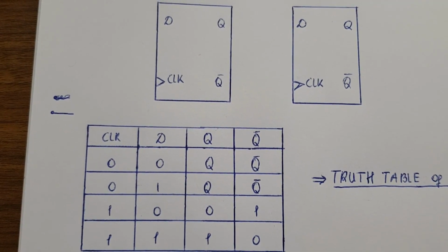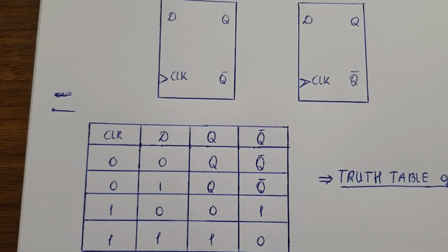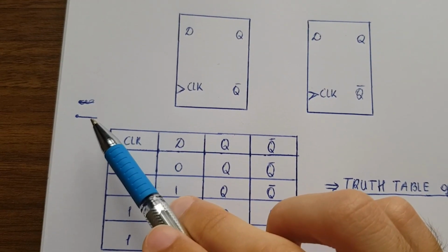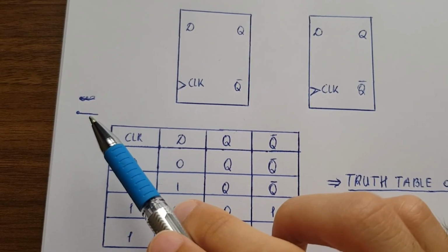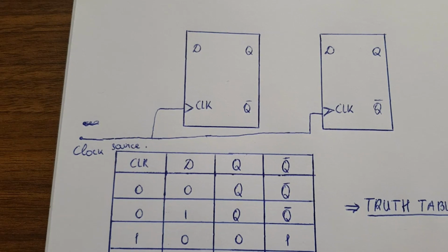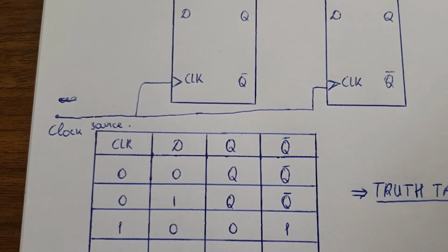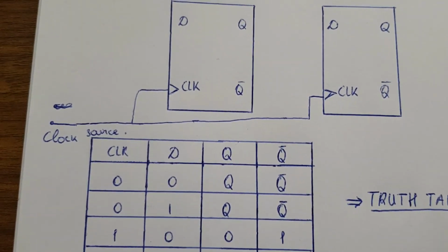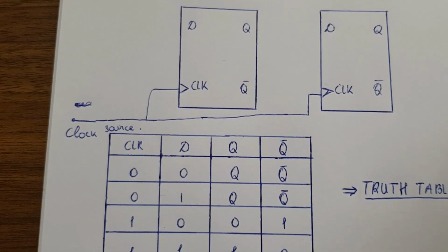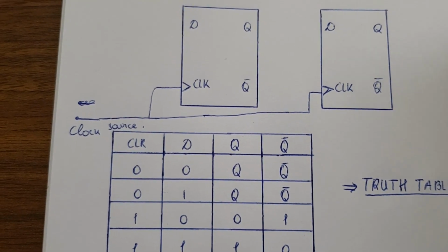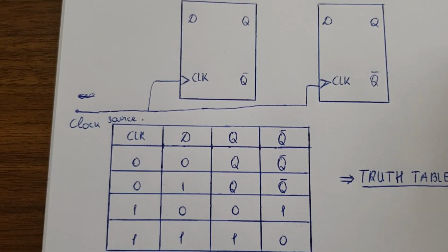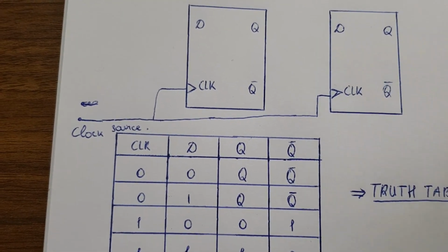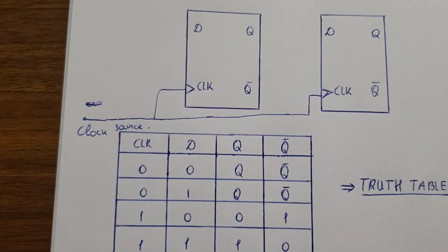So we said that in order to construct the synchronous counter, we have to feed all the clock inputs from the same clock source. Let's do that. But how do we connect the other inputs and outputs? We will have to construct a truth table for that, and we will use the Karnaugh map method to get the proper logic expressions. So let's do this.